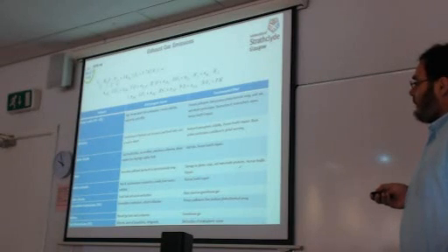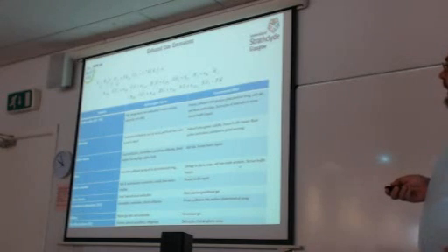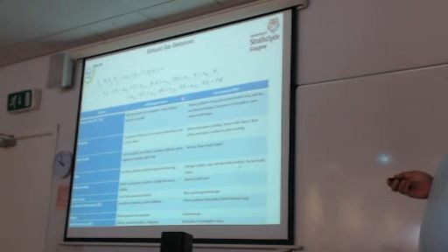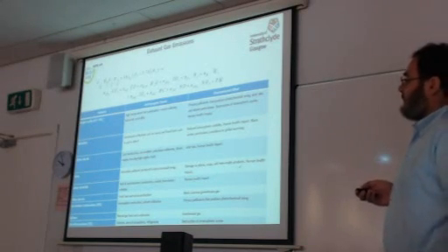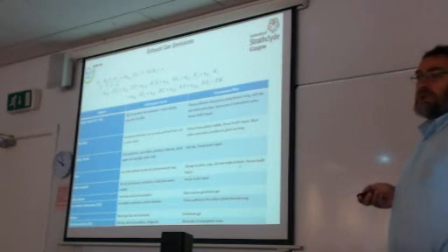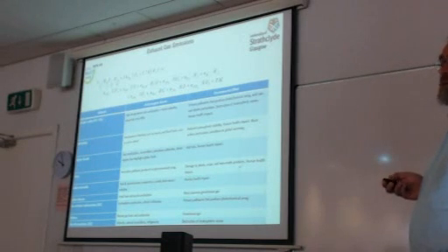And of course, we know that the emissions are dangerous and have consequences to the environment and to living organisms. And of course, there is a trend to reduce emissions. So up to now for shipping, the main initiatives are to reduce NOx, which means nitrogen monoxide and nitrogen dioxide, and SOx, which means SO2, SO3, and CO2, and the latter actually was initiated by the introduction of EEDI, the Energy Efficiency Design Index, and the introduction of EEOI, the Energy Efficiency Operational Indicator, which actually are both related to CO2, carbon dioxide emissions.